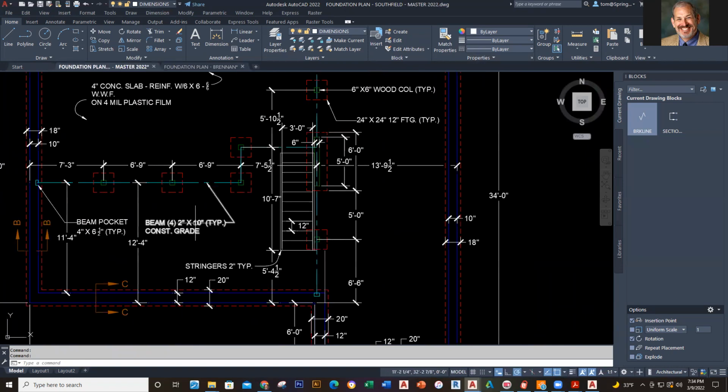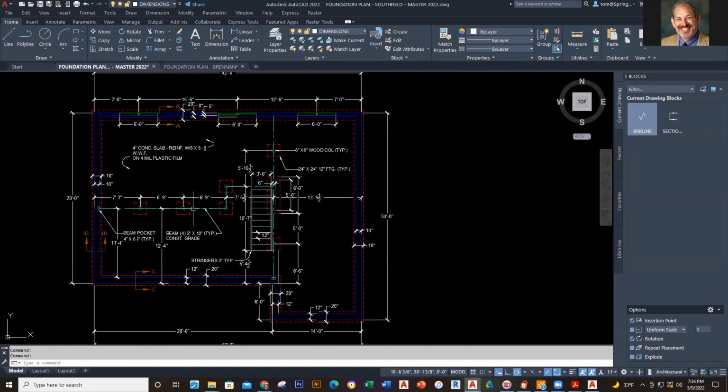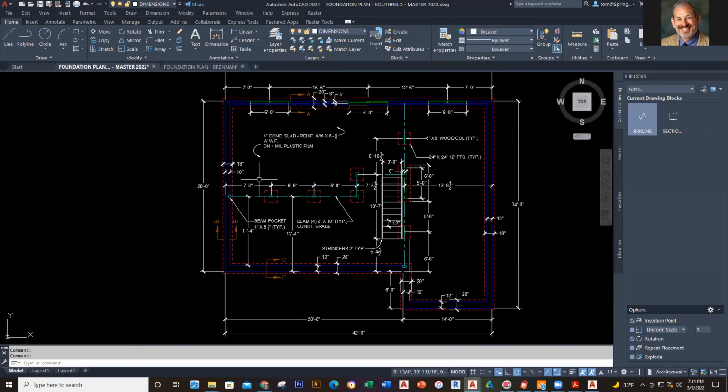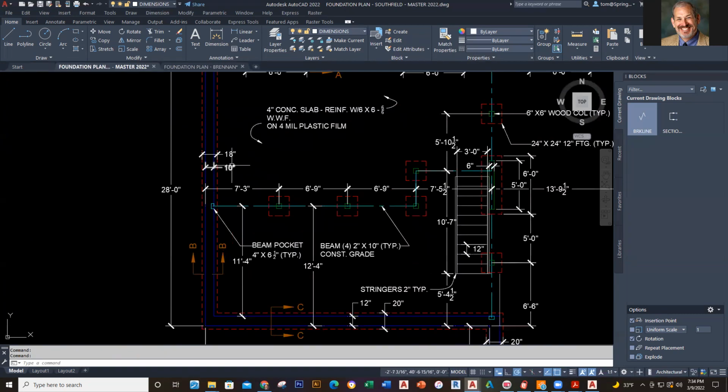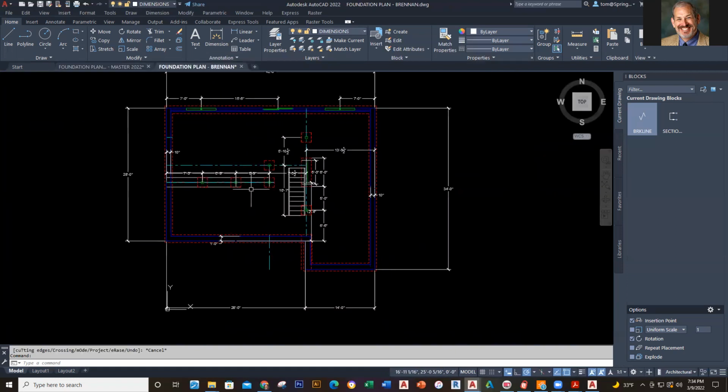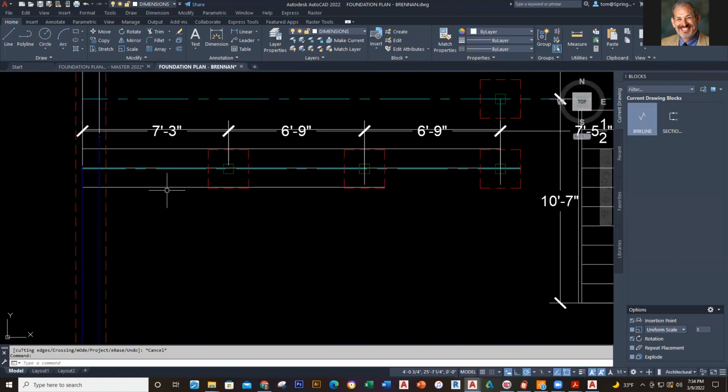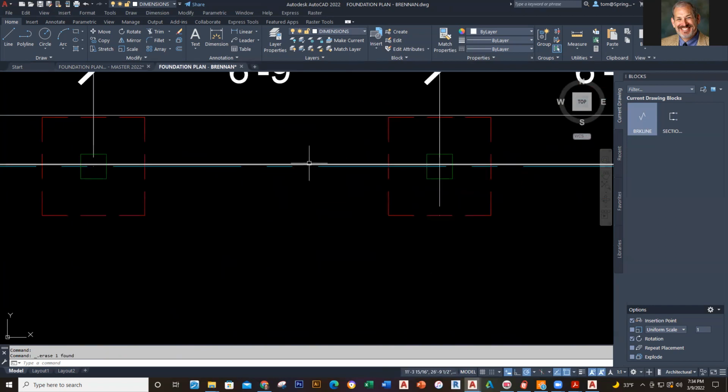Okay, then all I would need to do is put in my notation. Notation is set up in such a way as to be fairly straightforward. There's a couple things, I threw a couple gotchas out here. Over here what I've got is this says 10 inches, this is 18 inches. And when I measure this by default, you're gonna notice it doesn't actually do that. So I'm gonna get rid of these lines right here, delete that. And delete this one.